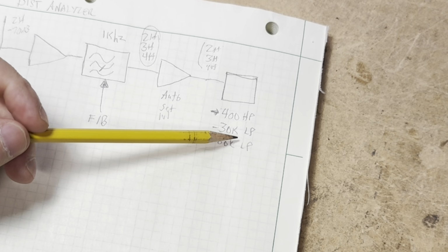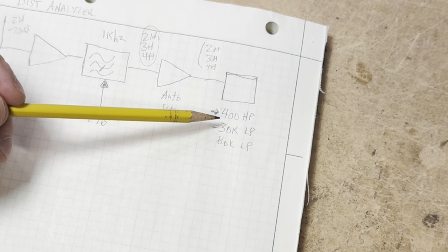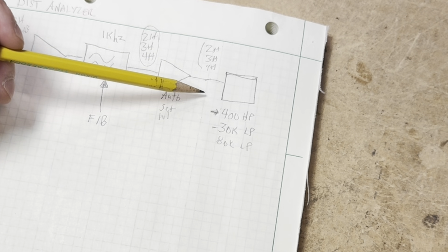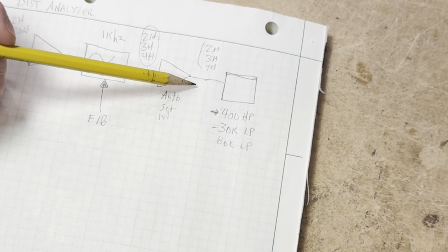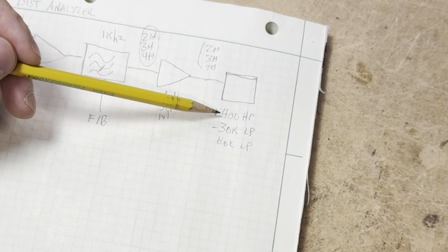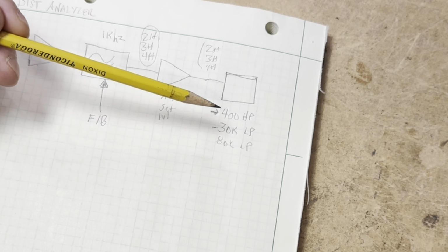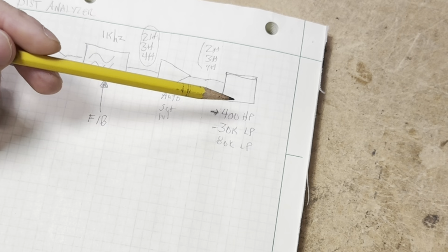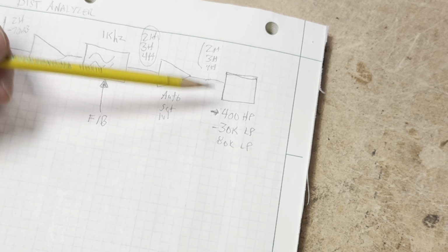There is a drawback to these filters in that they do alter the level of our harmonics. So if we're making a measurement that's close to especially the top of the audio range, maybe at 15 or 20 kilohertz, we may want to reconsider using these, especially the low pass filters, because they would give us an invalid distortion measurement in that they would positively alter the results.